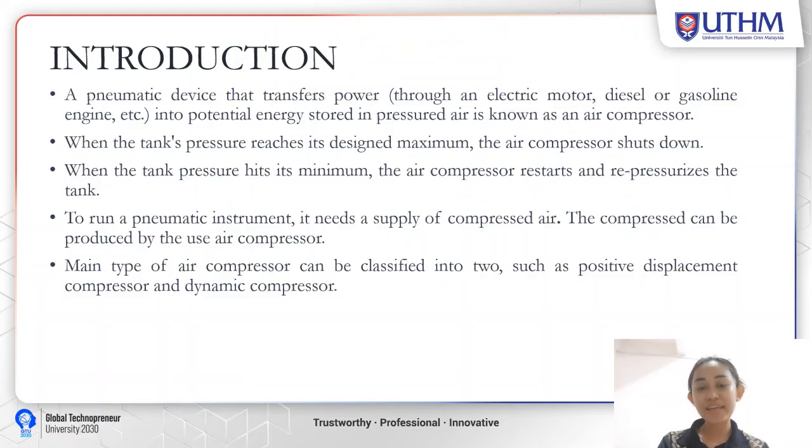Hello, my name is Lorani and I'm going to present about the introduction, objective and theory in Lab 5. Introduction. A pneumatic device that transfers power through an electric motor, diesel or gasoline engine, etc. into potential energy stored in pressure air is known as an air compressor. When the tank pressure reaches its design maximum, the air compressor shuts down. When the tank pressure hits its minimum, the air compressor restarts and repressurizes the tank.